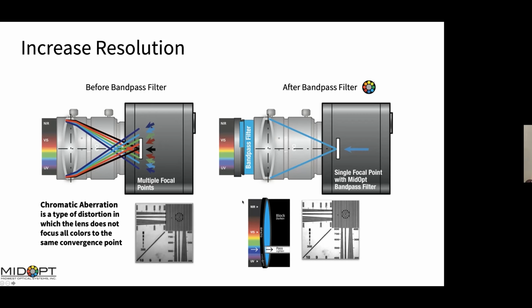But if you only cared about a certain color or a certain wavelength, you can limit the number of incoming wavelengths by using a filter. A filter would filter out the wavelengths that you're not really interested in, whether it be ambient or other wavelengths, and just pass the intended wavelength. So here, I'm filtering everything out and just passing the blue wavelength.